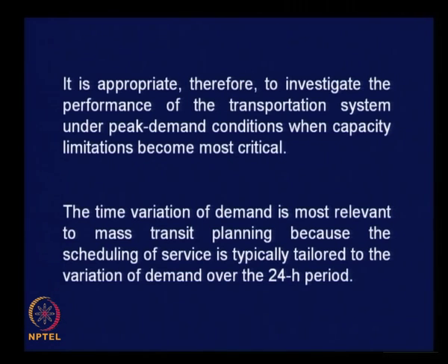Think of bus operators. Let us say they are operating bus service from different production zones to the activity centers near the CBD, dropping the people there in the morning. When the bus is returning, it is going to be almost empty. How do they ensure economic viability of operation? These are all the questions to be answered. That is why it is very critical for mass transit service operation.